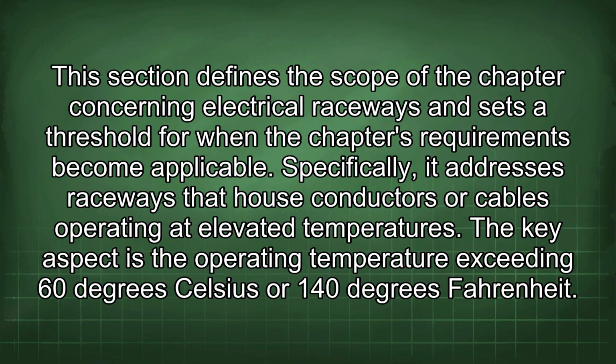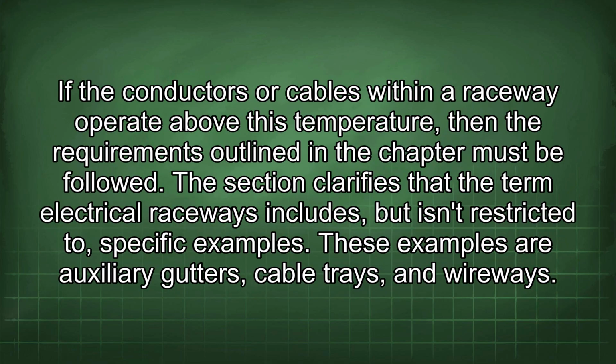This section defines the scope of the chapter concerning electrical raceways and sets a threshold for when the chapter's requirements become applicable. Specifically, it addresses raceways that house conductors or cables operating at elevated temperatures. The key aspect is the operating temperature exceeding 60 degrees Celsius or 140 degrees Fahrenheit. If the conductors or cables within a raceway operate above this temperature, then the requirements outlined in the chapter must